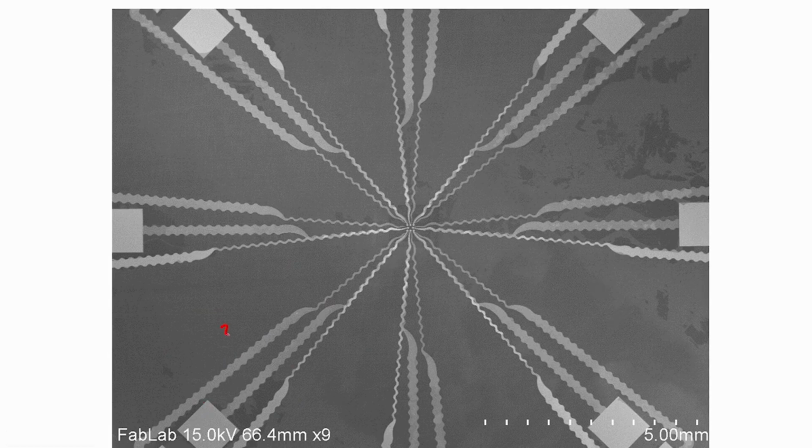You can see 3, 6, 9, 12, 15, 18, 21, 24, right. About 24 contact pads we have to fabricate, or we can pattern using chrome gold to take out the contacts from the piezoresistor and electrodes.